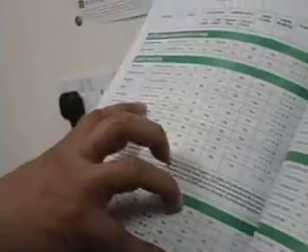North Foreland, latitude, longitude of the station, DGPS transmitting frequency 299.5 kilohertz, transmitting rate 100 bytes per second, reference station identification number 688. So go to main menu, go to system setting number 9. Now choose number 7, DGPS setup. Previously we did everything in number 6. Now choose number 7. Highlight DGPS setup, press enter.